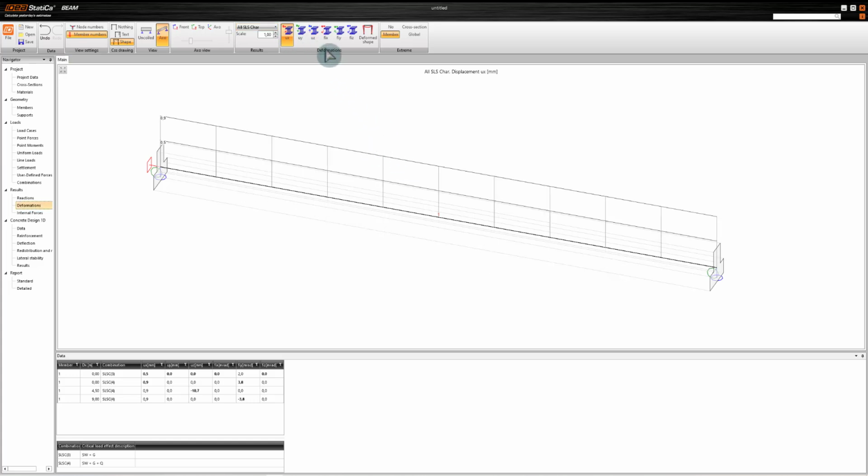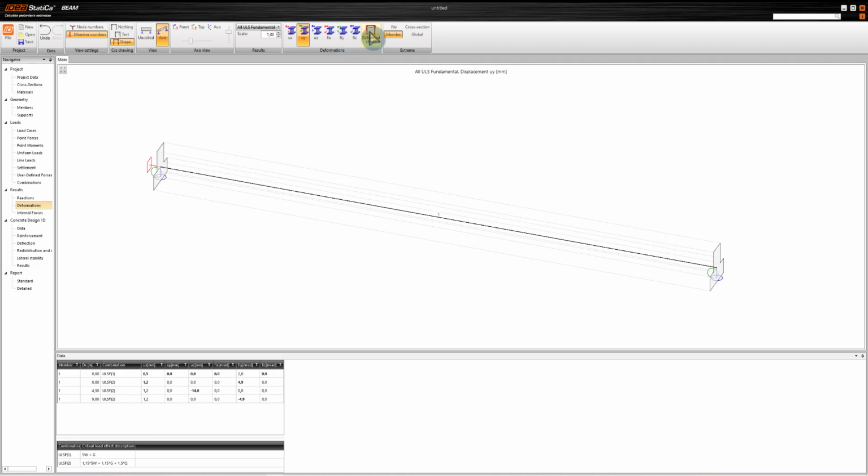We can check according to the fundamental. We can check all the forces from here. Again, if I go to the internal forces, from here I can check the shear force, normal forces, and Vz is the shear force, 185.2 is correct, and we can check the MY.